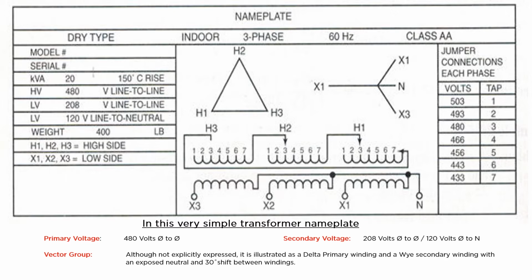You'll see that this diagram is a delta, that the terminals are labeled with H, so we know that it's associated with the primary winding. And then you see the 480 volts between the corners of the delta. Just think in terms of when we call something a delta, think in terms of a triangle, or if you're familiar with the Greek alphabet, you may think of it as a delta from the Greek alphabet.